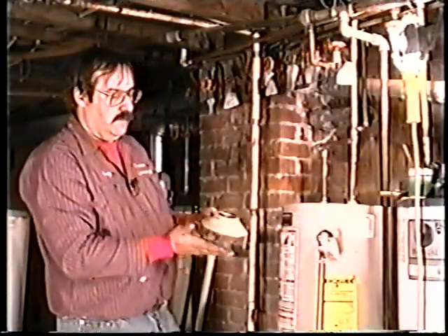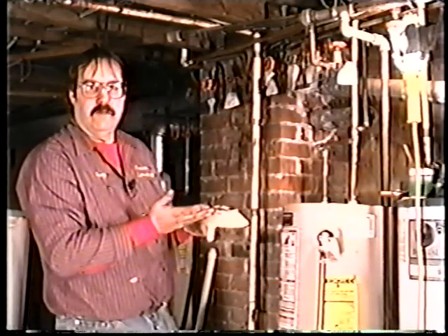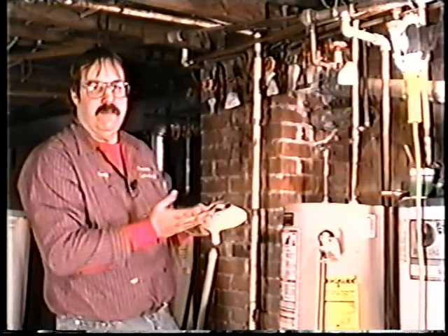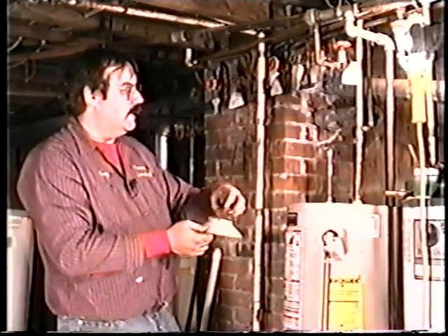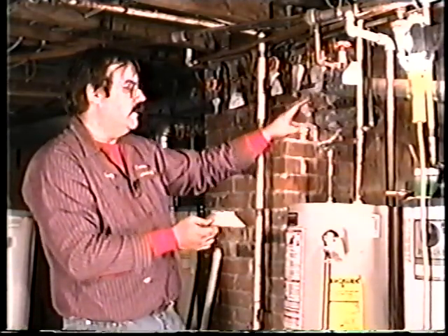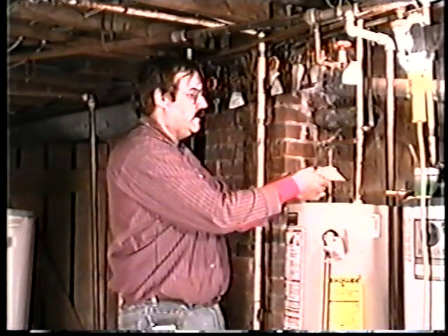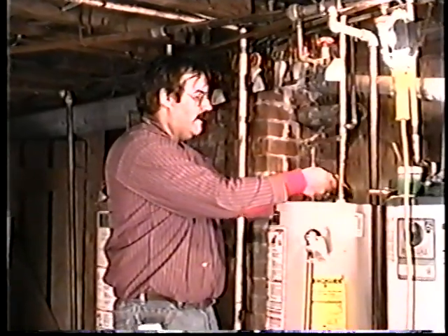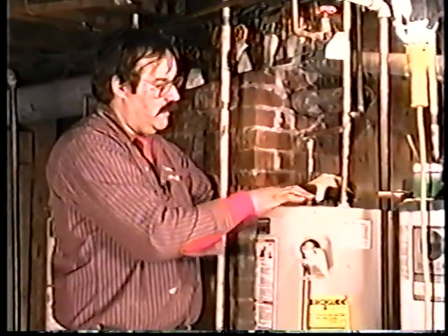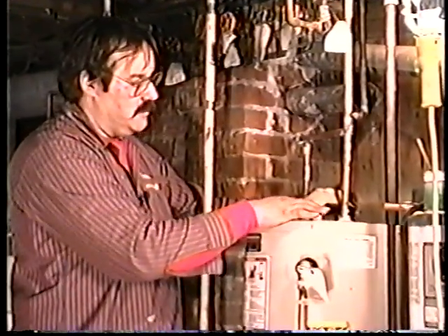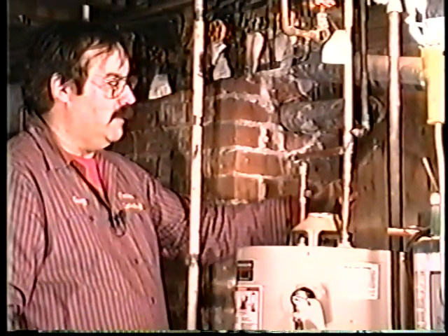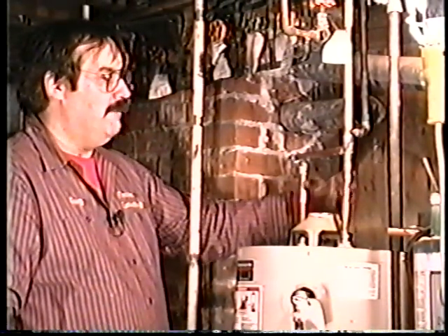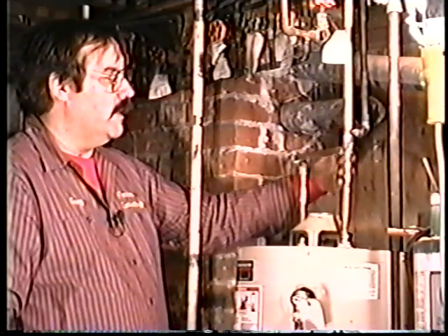The first part is the draft hood for the water heater. This is supplied by the manufacturers. This creates the draft needed to get the products of combustion from the water heater to the chimney. These attach to the top of the water heater. They usually have some holes drilled in the top of the water heater where these connectors, these legs go down into the holes. The last part is to take flue pipe, smoke pipe, and run it up and into